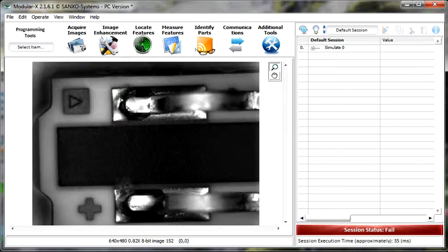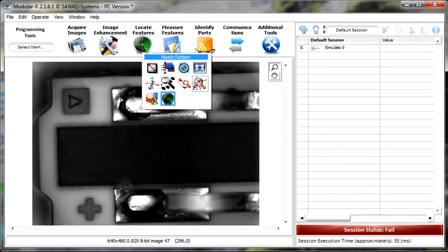I think the easiest way now is to look for two straight edges on the resistive material here, and then use the geometric functions to get the intersection of the edges and build up the coordinate system here. To do this, first we have to use the function called match pattern to position these straight edge functions. You can find the match pattern here.